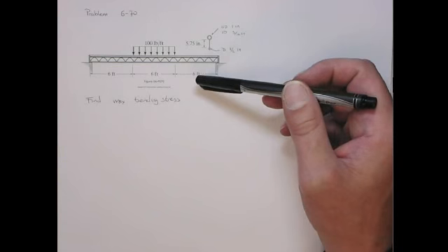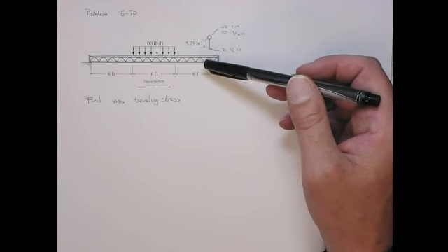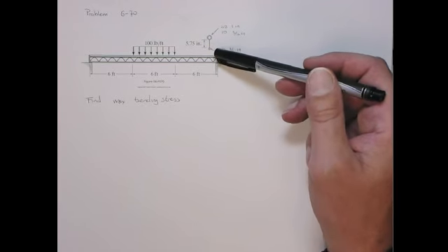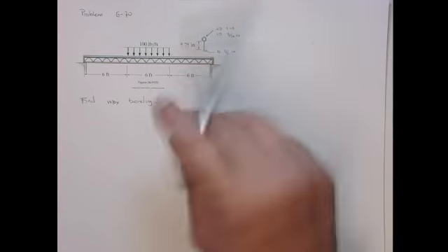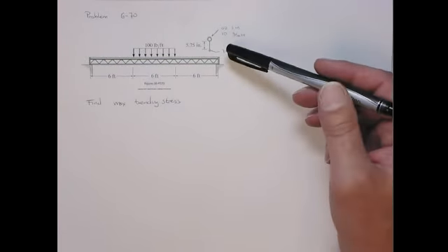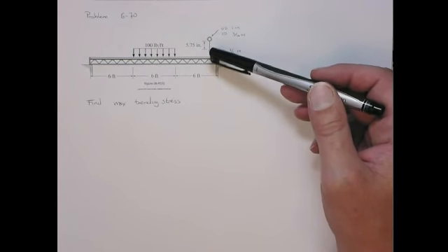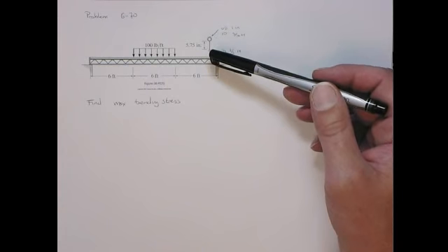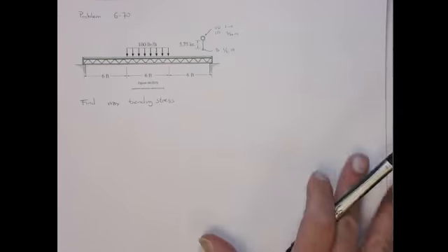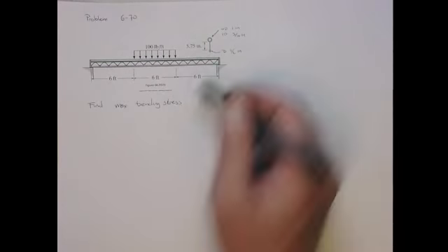You have this truss, well, really a composite beam if you consider it here. And this is the cross section of it. So it's two tubes connected by this wire brace through the middle. And the problem basically tells you can ignore the effect of the web, in the sense that the web doesn't really add any considerable stiffness or carry any significant load because it's very small. If you were to consider it, it would be a minor increase in the I of the whole thing.